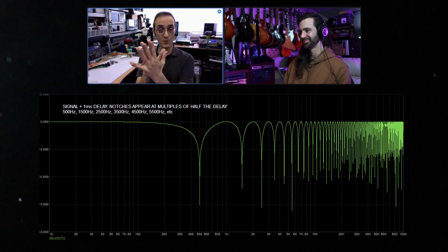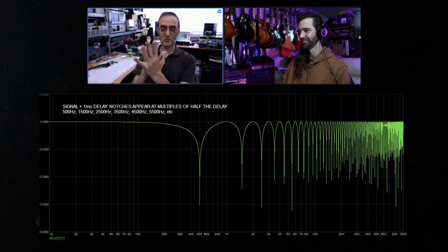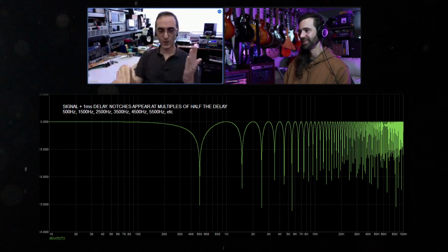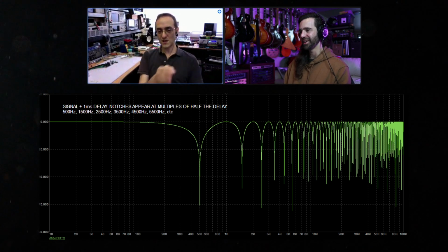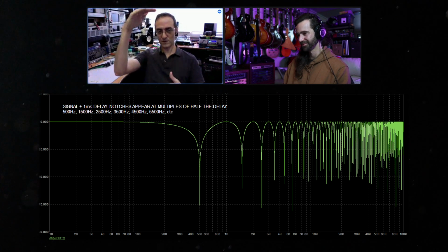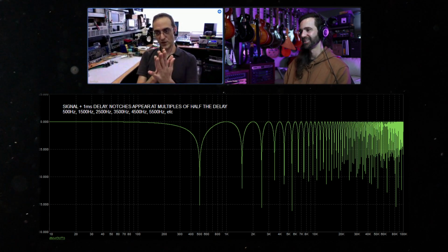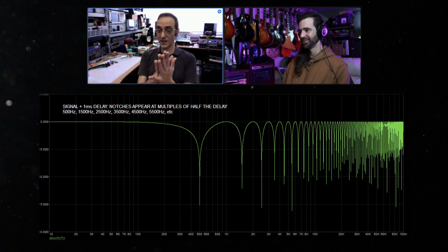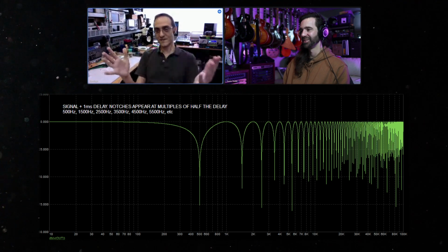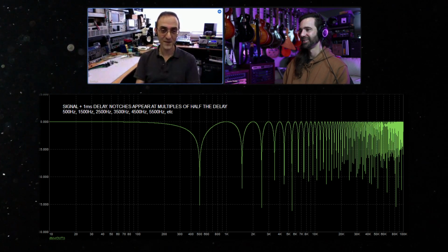Just imagine you compare it to itself at the same time. We'll add 2 times, okay? If one is out of phase, it will be 0. So you have a notch there. A notch means 0, and when they combine properly, you have double the output. That will be different depending on the frequency because you are delaying a fixed time, and the frequency is obviously a different number of cycles in the same time.